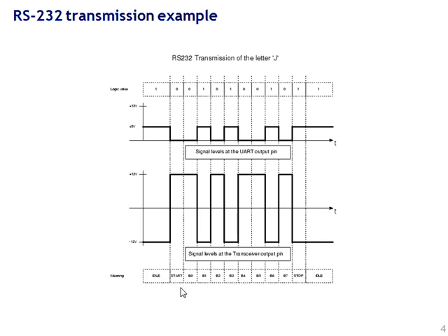For the peripheral, you're going to have another UART with its own internal clock. Those clocks also need to be synchronized, and they are synchronized by the start and stop bits. You need the framing bits because you have to know what time interval to sample the square wave at in order to figure out whether it's a 0 or a 1. If your framing bits are in error, you'll be sampling at improper intervals, like not in the middle of the timing interval, and then you won't know whether you've sampled the correct bit, 0 or 1.